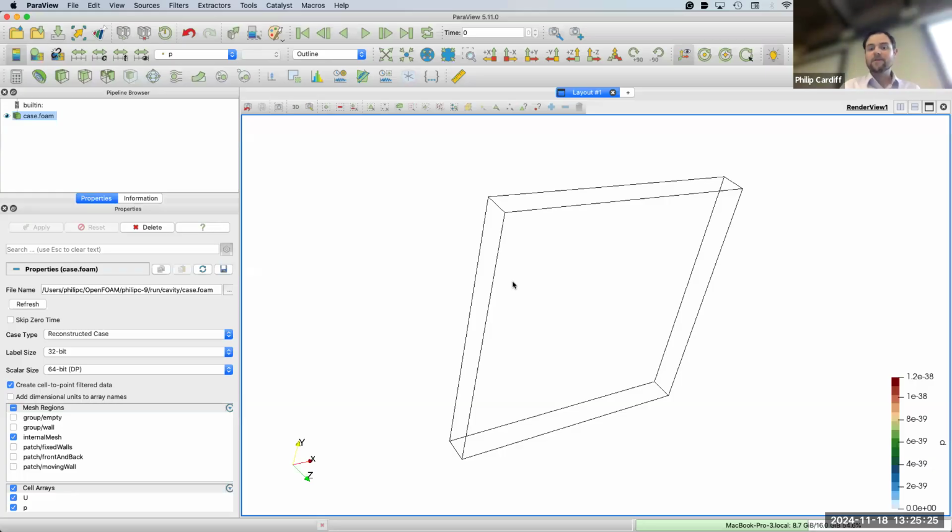So the way you do it for a block mesh is you will define one plane with the right hand rule. Sorry, that's anti-clockwise. Anti-clockwise with your thumb pointing in. And then the second plane, you should start from the first point on that plane that connects to the first point that you started on previously, and then go in the same direction. But it doesn't matter which plane you start at. That's just one way they've done it here.